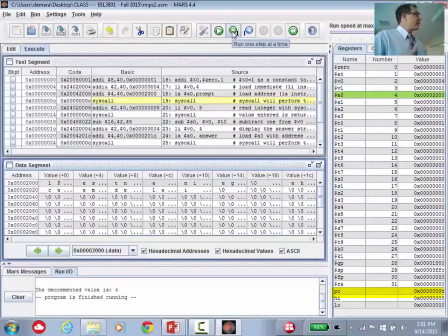And you can see now the program counter went to address C, which means the next instruction to execute is grabbing these bits. Well, it's a coincidence. Okay, but in any case, that's 000C. You can see at any address is actually the bit sequence for syscall.